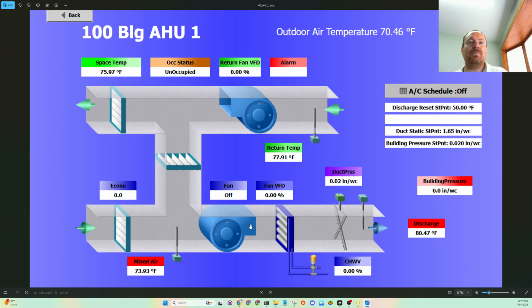The most ideal thing is that the air handling unit should be making up that air for exhaust systems and then conditioning it as well, through a filter and then through some sort of cooling coil if it's humid outside like it is now.